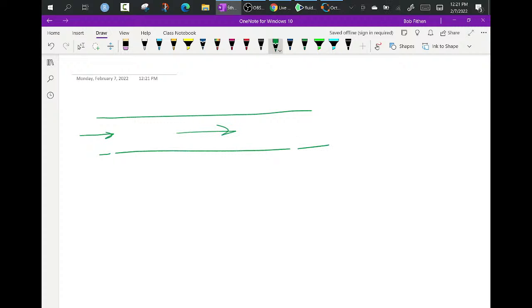And what you want to know is you want to know P1 and P2. Well, it turns out in reality what happens is, in order for the water to go from left to right, this one's got to be slightly bigger than that one. And so what do you do? You just string a manometer off there.